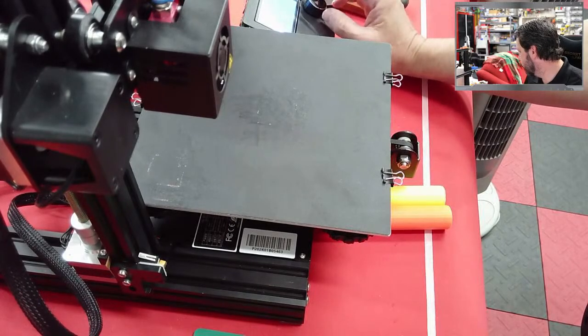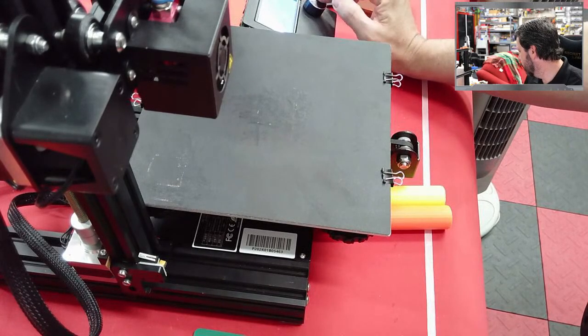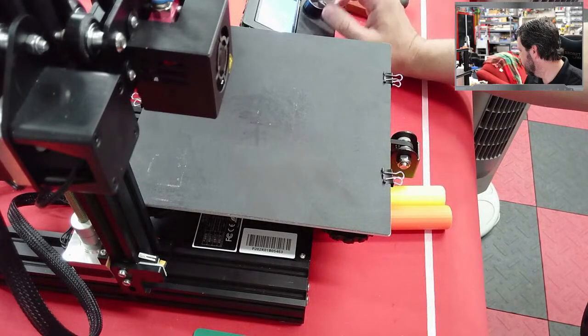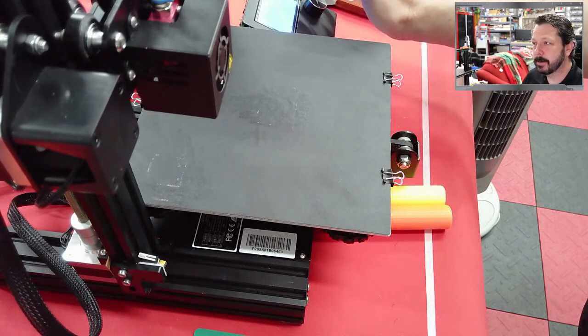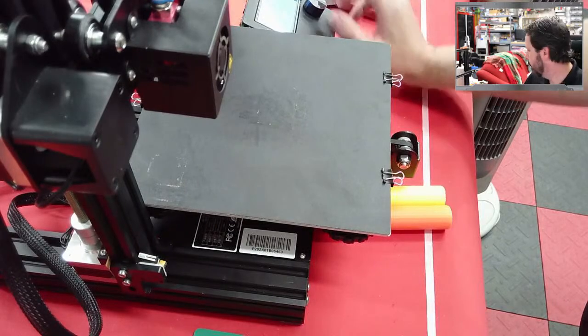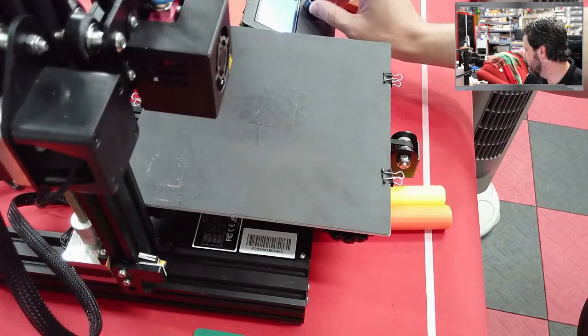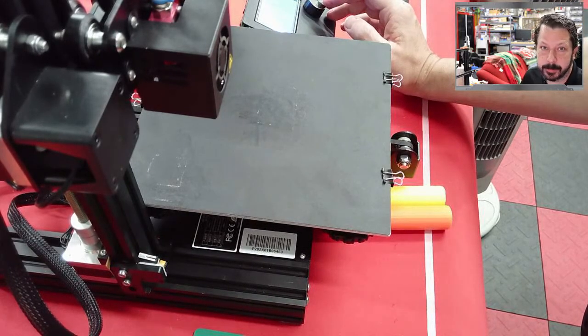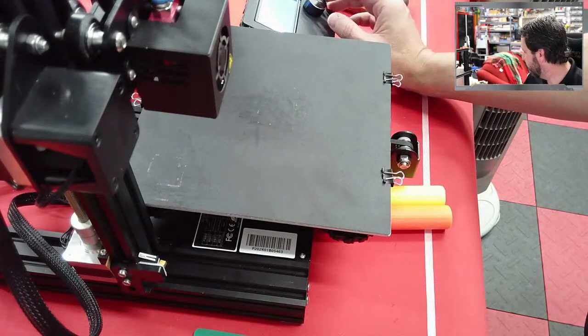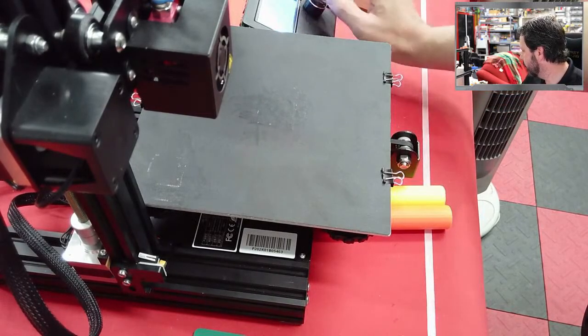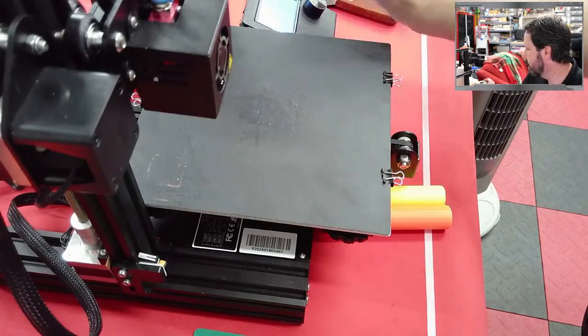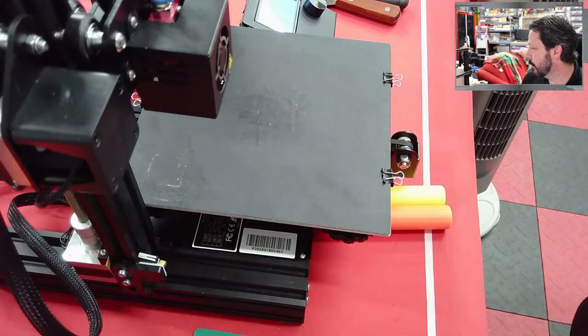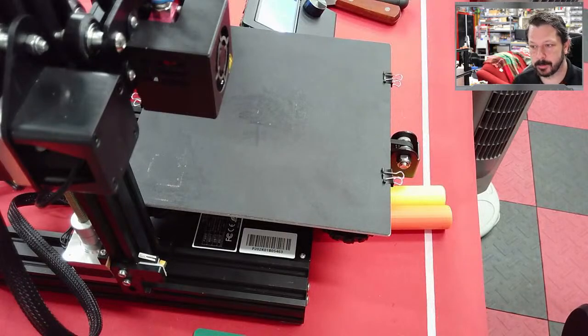Control is the option, and then Motion, and I have steps per millimeter. I can change X, Y, Z, and E steps on the screen right here. You just have to remember to store the settings. So in the screen before this one, there is Store Settings. Once you change them to whatever you need them to be, do your calibration, then you store them here. So you don't need the terminal to change the E-steps, and it's probably the one that will have the greatest effect on making your prints a little more accurate.